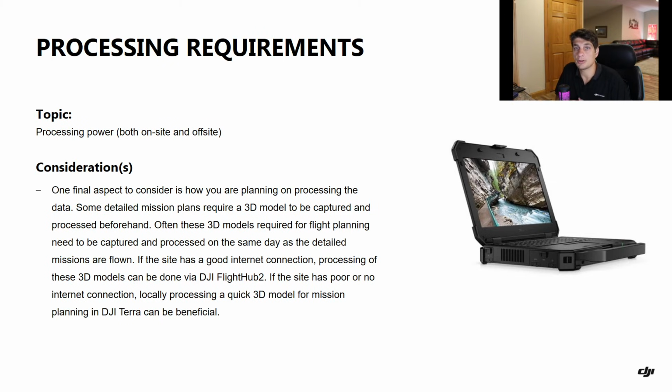Also, once we have captured the entire site, it's then important to know: am I going to be processing this locally? If I'm going to be spending money on a processing computer or a gaming computer essentially to be able to process that data set, or am I going to be utilizing a subscription-based service where I'm going to be uploading that data to the cloud for them to process? Obviously, a subscription-based service is going to cost a little bit more when you're talking about a monthly or an annual bill to be able to process and host your data, but you don't have that large upfront cost of building out a computer or a PC that's going to be able to process these potentially large data sets that you have.